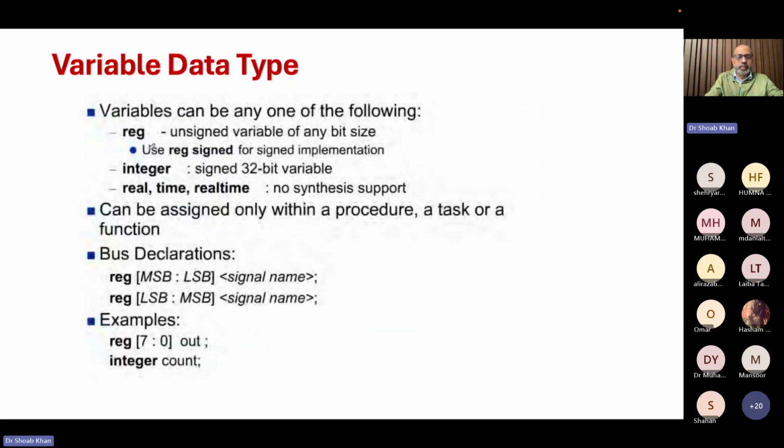On the other hand, reg is a type of variable where you can do multiple assignments. You can say a is equal to 3, then a is equal to 4, then a is equal to 5. So in this order, we'll keep changing the values. And obviously it is important once you are testing your design: you've got to keep changing values and keep assigning them different values.